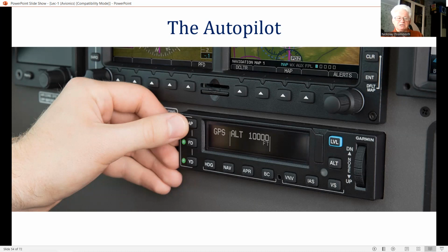In military applications, the autopilot system, in conjunction with a suitable guidance system, can provide automatic terrain following or terrain avoidance. This enables the aircraft to fly automatically at high speed at very low altitude, approximately 100 to 200 feet, so that the aircraft can take advantage of terrain screening and stay below the radar horizon of enemy radar.